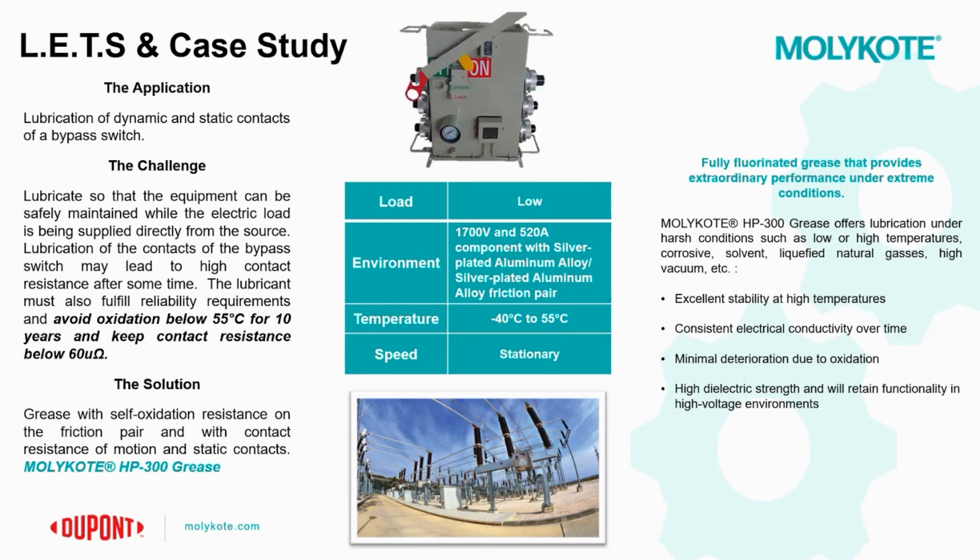As such, we would probably want to select a grease with a linear PFPE base oil, and one such grease within the portfolio that meets those requirements would be HP300 again. So this grease is a linear PFPE base oil that is PTFE thickened and has PTFE solid lubricants. And because this is a fully fluorinated grease, it would perform pretty well under very extreme, more specialized conditions.